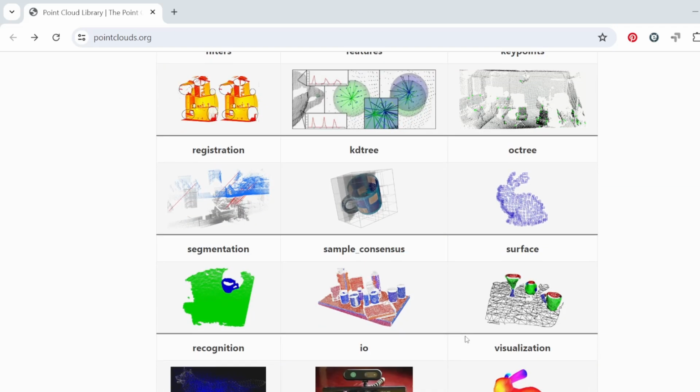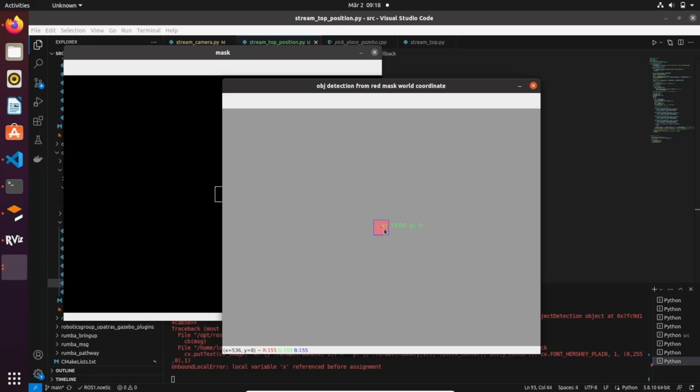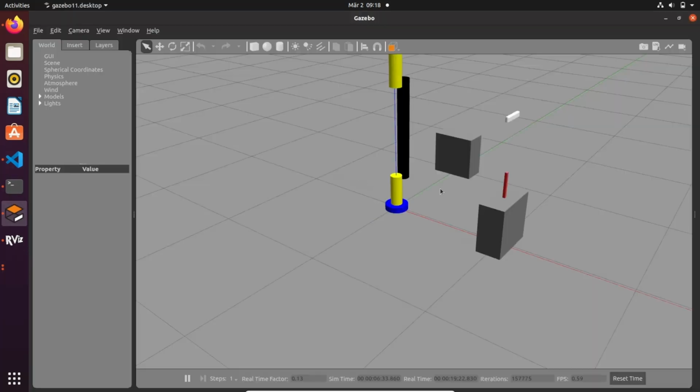So if I want to give you an example, in OpenCV we have done a video so far, and we got a 2D image from a camera that was subscribing to the topic image raw. And if you remember, we have used the tools available in OpenCV to manipulate that image for our interest, like crop an image, create a mask based on the color, apply an edge detection, find the points of a square, and so on and so forth.